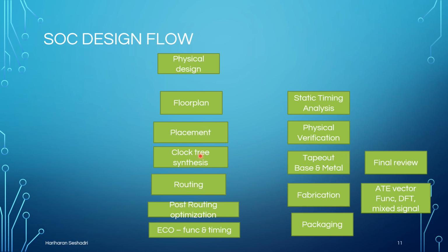Then the clocks are built. There are so many clocks in that chip, hundreds of clocks. You have to do something called clock tree synthesis. Clock routing should have less skew. If you know what is setup time, hold time, you will understand what is a skew. There are important concepts that college should teach. They are a prerequisite for any chip design course, VLSI course, right? So clock tree synthesis, right? Extremely important.